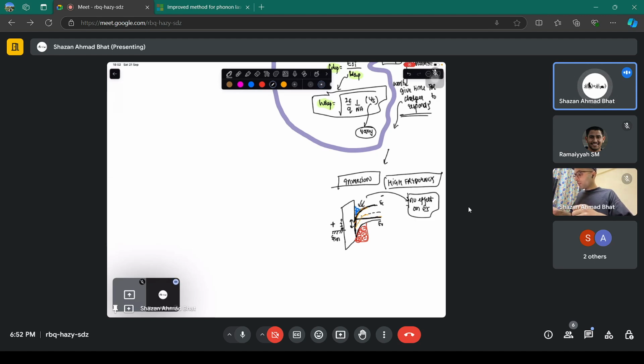Why? Because you have to see where these electrons came from. They came because of the generation mechanism, generation plus recombination, particularly generation, from the bulk. I showed you in the previous picture that from the bulk, an electron gets generated here, leaves a hole, and then it drifts down and comes to that potential where it inverts the surface.